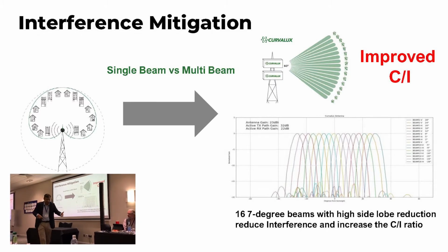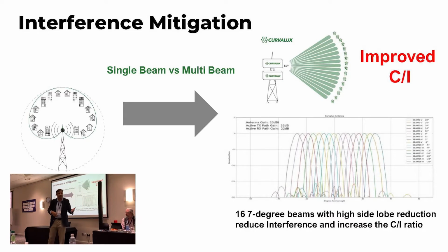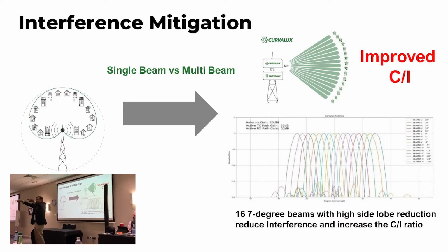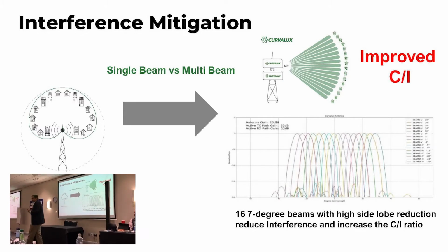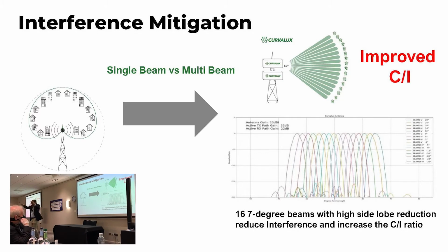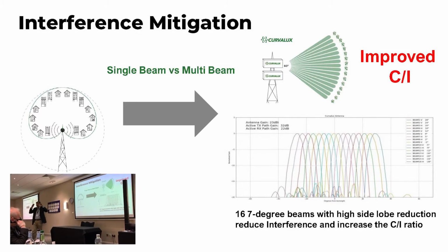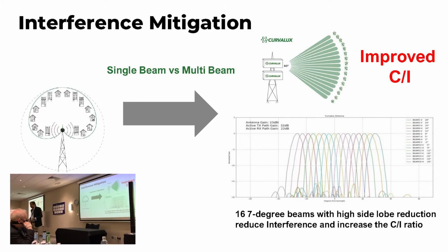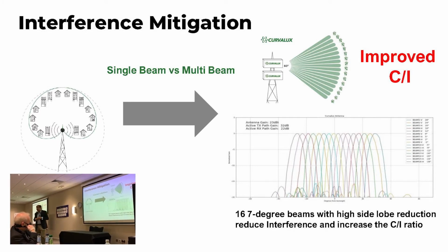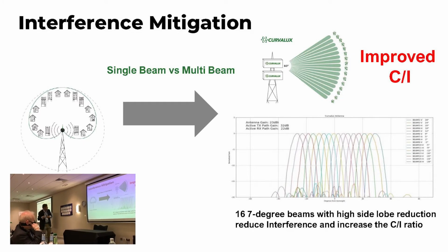And there's another technology people are using, which is quasi-omnidirectional, which is not truly omnidirectional, but uses different panels and makes it look like an omnidirectional. But omnidirectional has a limitation in terms of the gain. And you are transmitting power to everybody, even to those people who are not interested to hear you. And you are listening to everybody, including those you are not interested to hear from. So your I will always be high in omnidirectional.